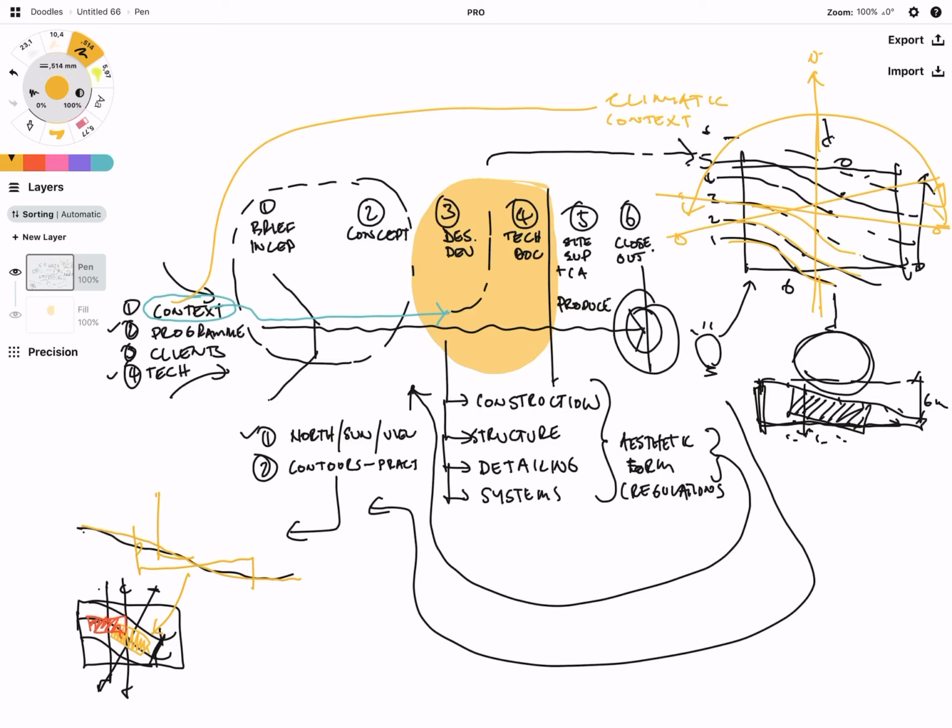So a less steep angle, if you had to cut and fill this building, would end up reducing the amount of cut and the amount of work going into cut and fill, versus the angle slightly oblique off contour, because the distance from here to here is different to the distance over there and there, which means that it's much steeper going at an oblique angle, which means that the amount of cut and fill that you end up doing here is going to be a lot more.